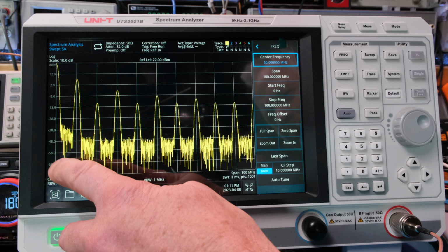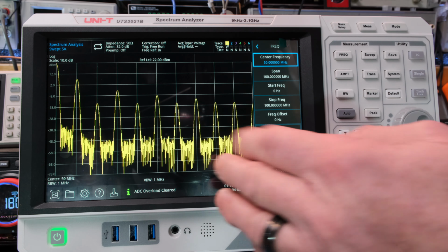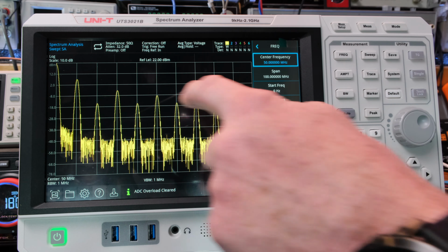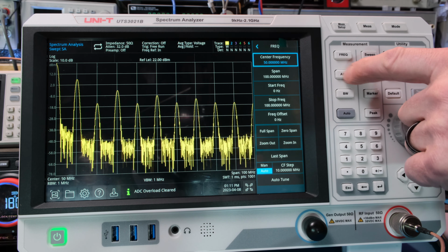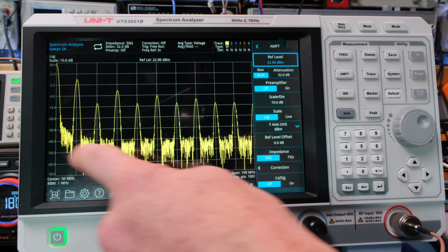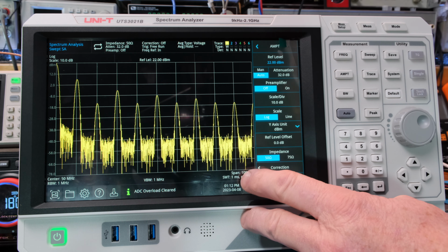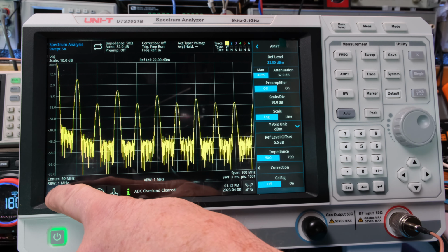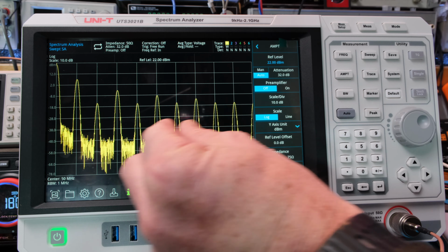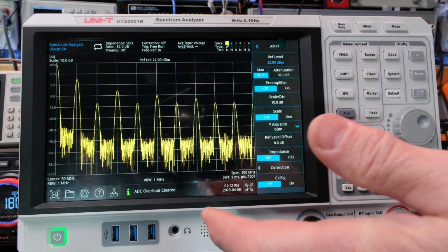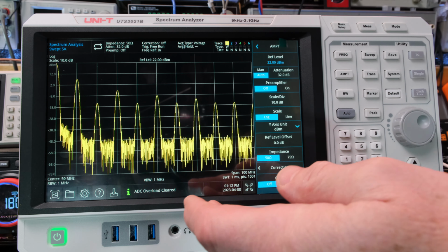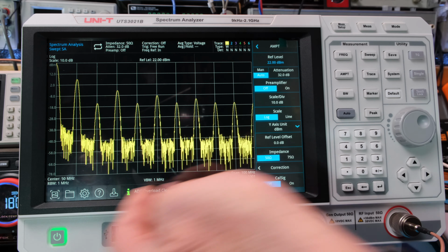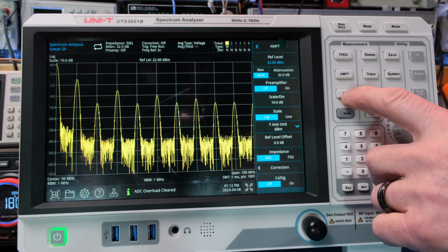Now, our noise floor, by the way, is down here, minus 38. Not super impressive, but that's because we've got big wide pulses here. If we come back over here, amplitude, let me just finish this up because the frequencies cross here. So the span is 100 meg and 50 meg is here. But see this resolution bandwidth, 1 megahertz. So we're only looking at 1 megahertz bandwidth. That's not that awesome, right? So instead of kilosamples and stuff like that, like the digital scope, it's talking frequencies. Now, what we can do is come over here.